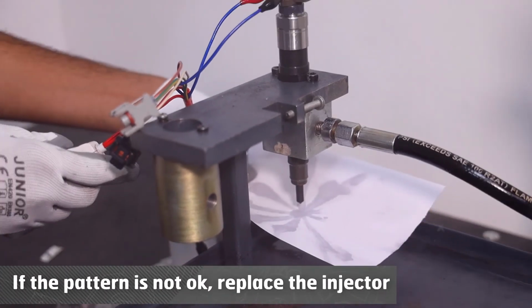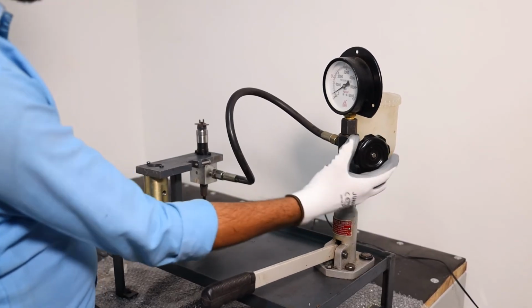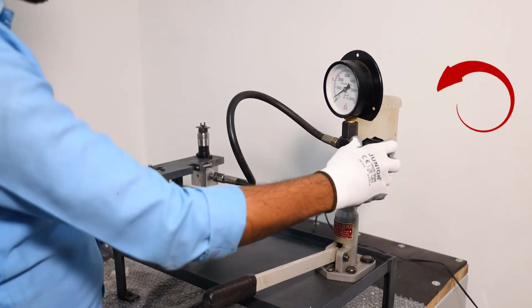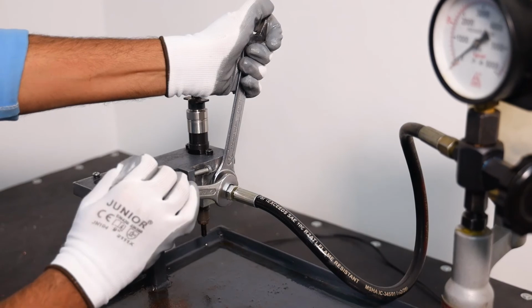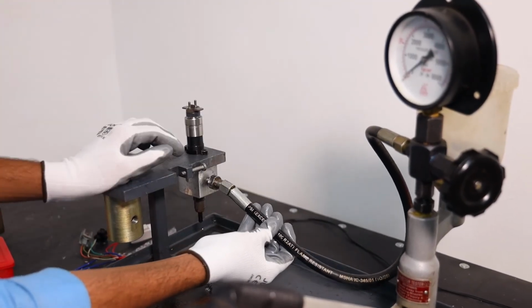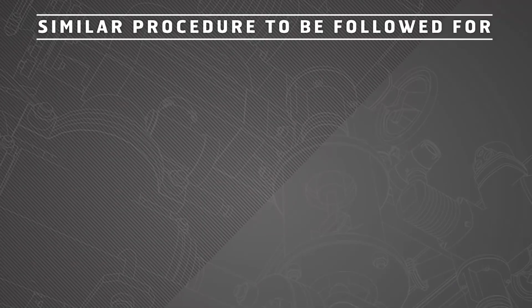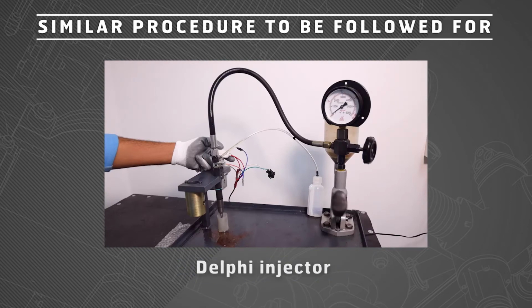If the pattern is not okay, replace the injector. Simultaneously, check the back leak of injector. After checking the spray pattern, rotate the pressure relief valve anti-clockwise and then remove the connections as shown. Similar procedure to be followed for BS6 Bosch and Delphi injectors.